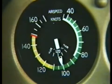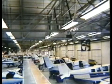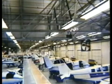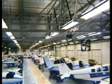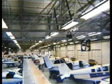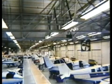Incidentally, were you aware of the fact that some general aviation airplanes have the color-coded arcs on their airspeed indicators painted in calibrated airspeed values, while others display only indicated airspeeds? It's a fact. You see, starting in the latter half of the 1970s, most aircraft were built with airspeed indicators that had color-coded arcs marked in indicated airspeed rather than in calibrated airspeed. Calibrated, of course, is indicated airspeed corrected for position and instrument error. Now, how is that significant?